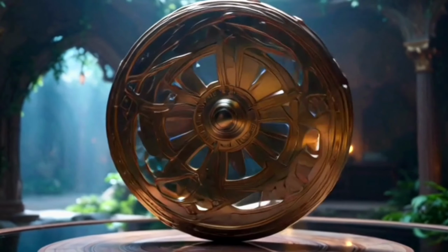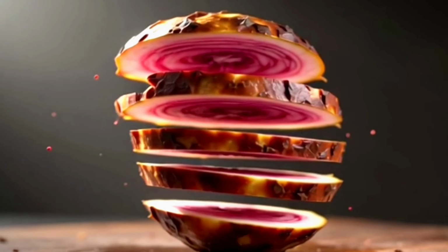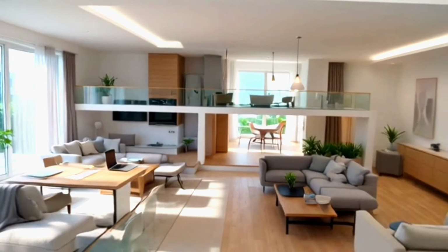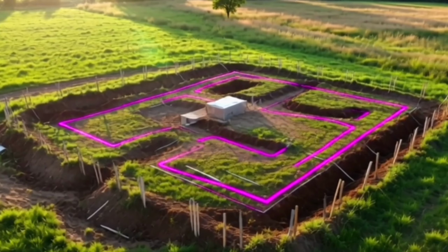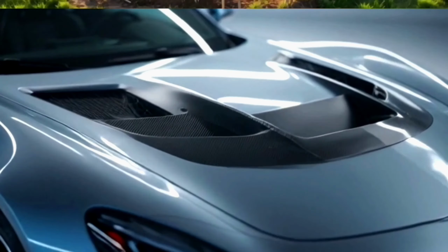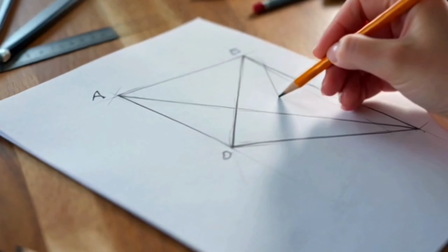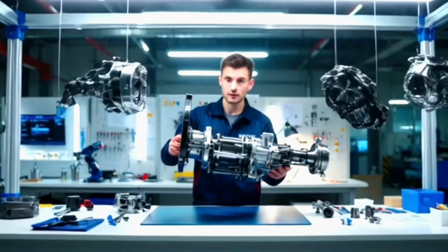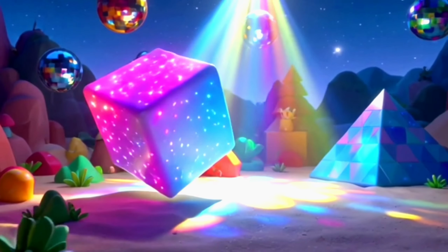The base versus the boss. Note that the base is only 12 mm thick, but the cylindrical boss rises to a total height of 50 mm. The transition: where the 12 mm rib meets the cylinder, the projection line ensures the tangent point is mathematically accurate. Hatching is where most students lose marks. Think of the hatching lines as a signature of solid material. Rule 1: use a 2H pencil or a thin line weight for hatching. It should never be as thick as the object's outline.